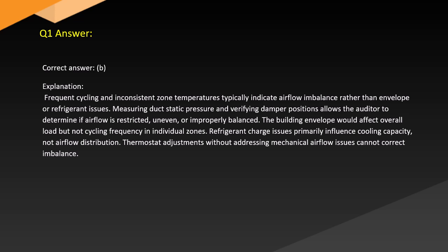Refrigerant charge issues primarily affect cooling capacity, not airflow distribution. Thermostat adjustments without addressing mechanical airflow issues cannot correct imbalance.